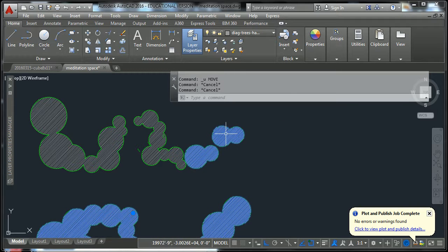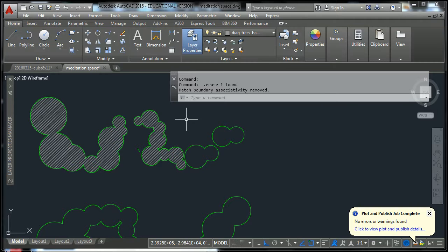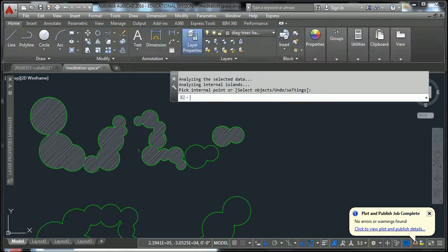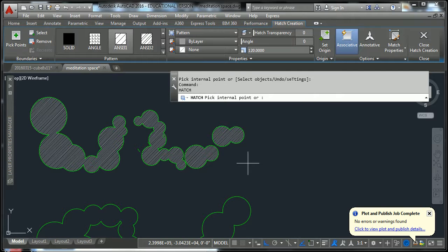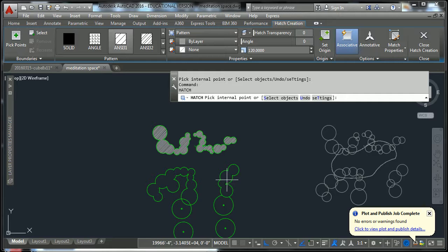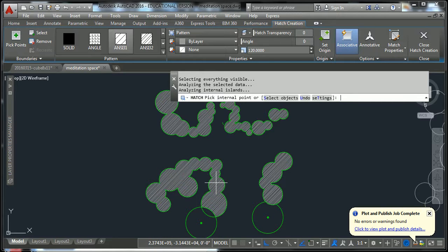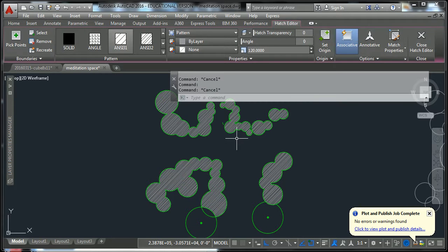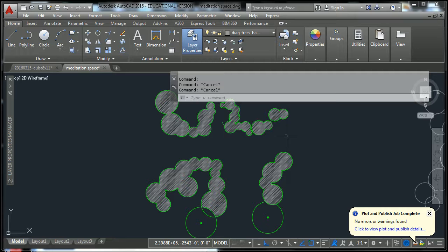I'm going to undo that, and I'm going to keep each of the hatched areas as its own separate zones. So enter, so that all my trees, or block of trees, or groves of trees, or whatever you want to call it, is its own set of hatch. So if I do need to change some of these, I'm not going to affect all the rest.